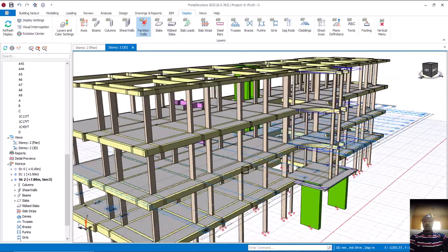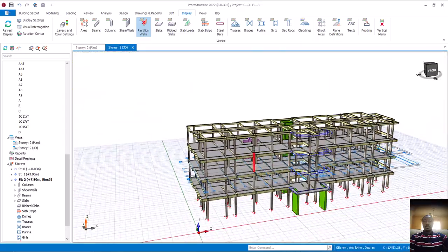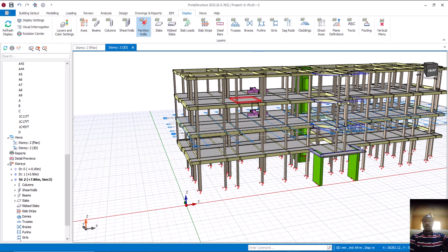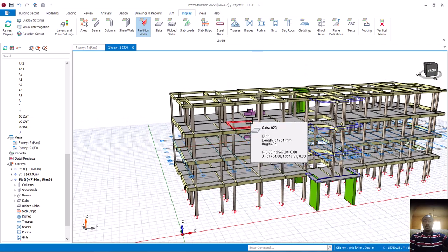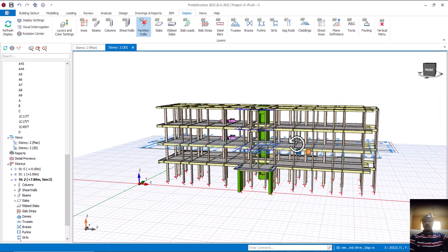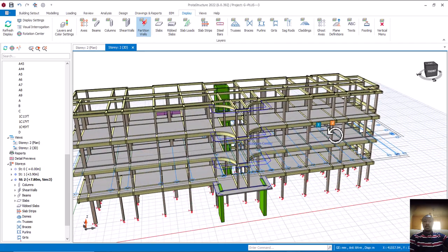As I worked on this one, automatically it was taking effect on the next floor. Can you see now? Let's assume I have up to a 5-story, 10-story. Understand? As I have worked on this one now, everything will appear on all of them. Which means that as I'm done with this, I'm done with this, I'm done with this. If I go to the next one now, work on this other side, the same thing is going to appear here. Anything I'm doing on the slab also takes effect on that floor.